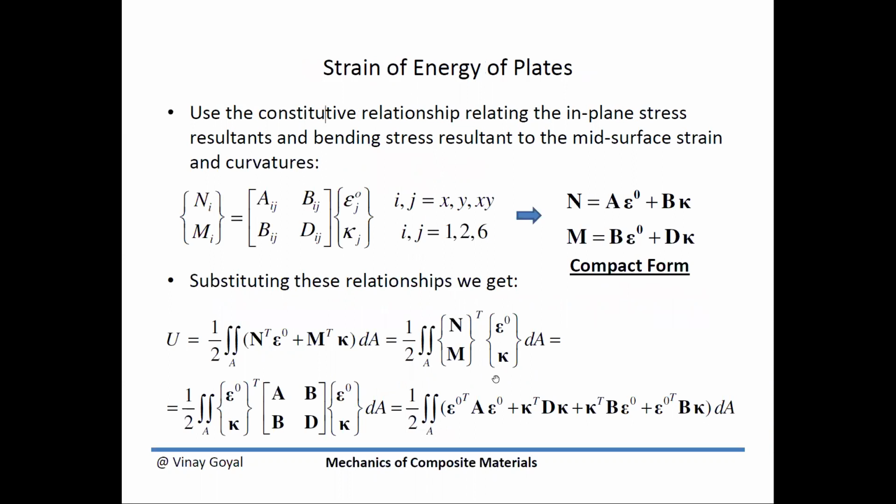So we can now use the constitutive law that we have previously discussed, and I don't want to go through the ABD matrix again. I invite you to go back to the YouTube lecture where we discussed where this came about, but we can use the constitutive relationships relating in-plane stress resultants and bending stress resultants to the mid-surface strains and curvatures using this formula.